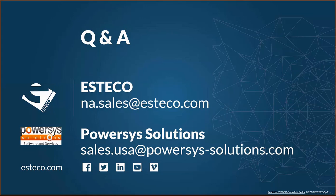Thank you, Adarsh. Just wanted to add to that. As others mentioned here, we used parallel two nodes to run structural and electromagnetic. So in this process, the longest running simulation defines the total time, because the electromagnetic in this case is 23 seconds, so it finishes before structural. So the entire simulation time is dependent only on the structural analysis. Excellent point, Dheeraj. That's a good point.